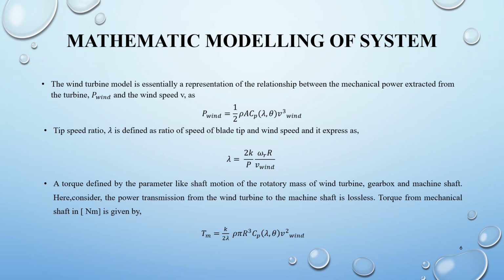A variable speed system, as opposed to the fixed speed system, maintains the generator torque relatively constant and adapts the generator speed to account for a variation in the wind. A variable speed wind turbine electrical system is more complex than a fixed speed wind turbine.